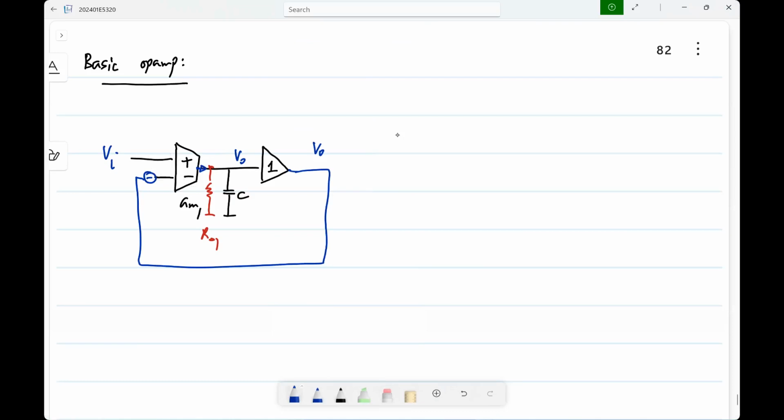Now we had one particular fix for the problem. That is, instead of just pushing the current into this impedance to develop a voltage, we made a proper current controlled voltage source. A current controlled voltage source gives a low input impedance. So this output voltage doesn't appear across RO1. So that was the idea behind the previous set of improved op amps that we realized, right?